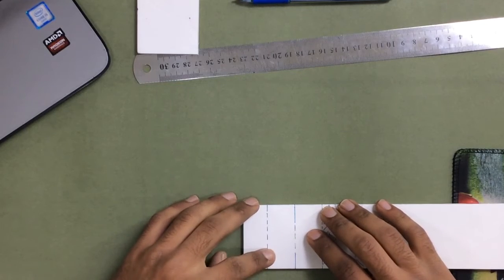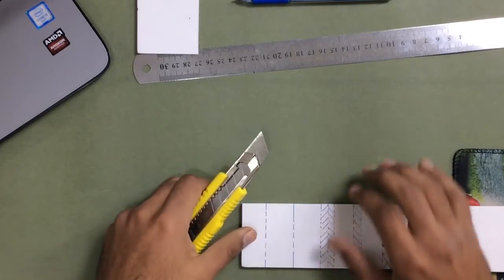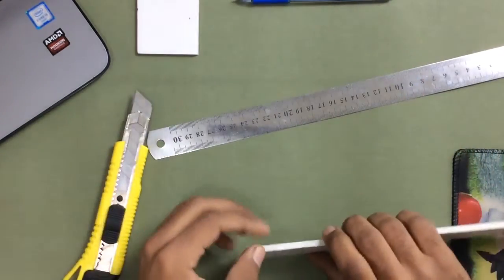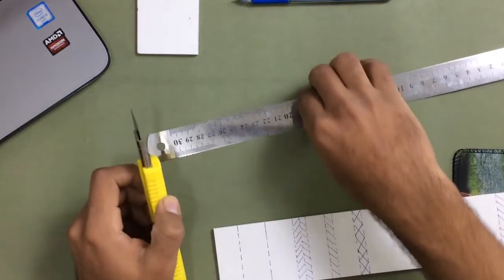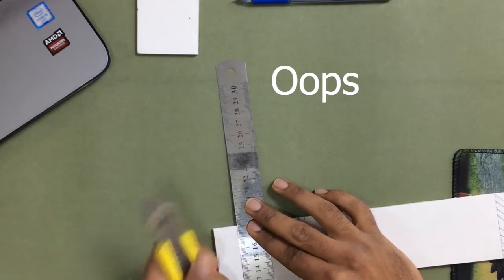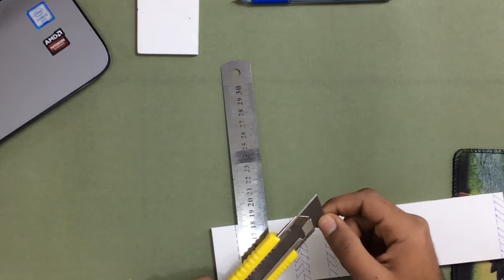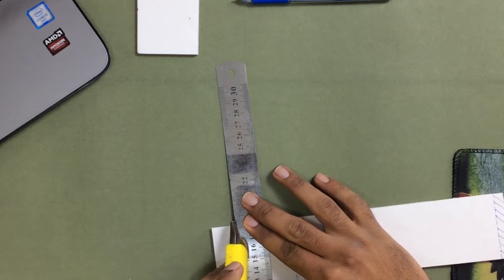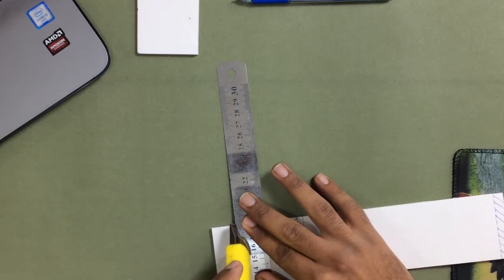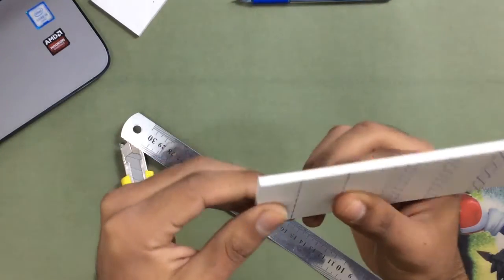The first one is a 50% score cut. So let's take our blade, and the 50% score cut means that you have to cut the foam board half. Like, you don't have to go through the foam board, you just have to cut half of it. So just take your scale, and if you can manage the blade so that you can open it all, or if you can't manage, just take its tip out so that you can't go through the foam board, and just simply make a slight cut. So I haven't gone through the foam board completely. I just cut half of it.